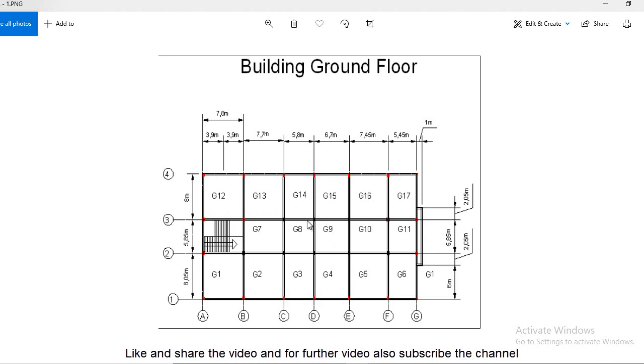And similarly due to geometry, you see the moment. So in the final stage, when you are going to design any column, you have to sum up these moments, because some moments cancel out each other's effect.